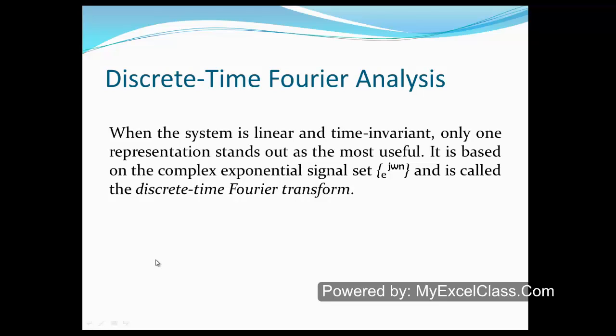This convolution representation is based on the fact that any signal can be represented by a linear combination of scaled and delayed unit samples. Similarly, we can also represent any arbitrary discrete signal as a linear combination of basis signals. Each basis signal set provides a new signal representation. Each representation has some advantages and some disadvantages depending on the type of system under construction.